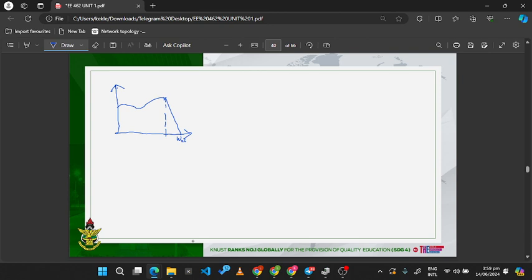Then the load torque will be given, since we have the equation, we know it's linear, and it's something like this. So our operating point is simply the point where these two lines, the load and then the drive torque, will be equal. We have our load torque at 0.06 times omega r. So we need to find an equation for the electrical torque.